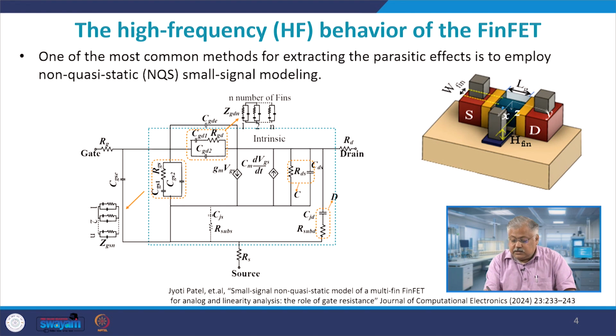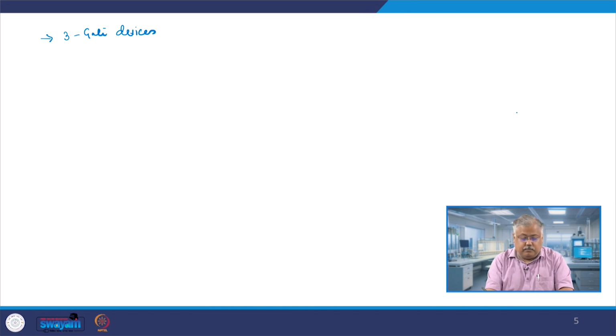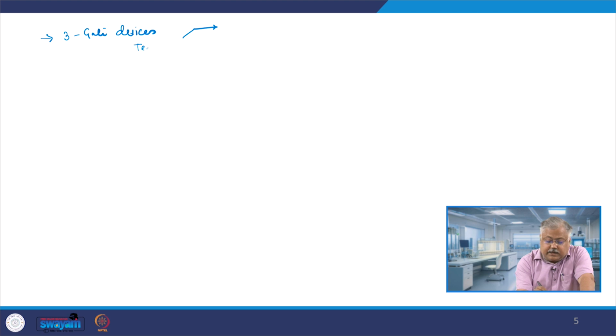So if you make this top gate oxide layer very thick, the gate loses control over the top gate, and a tri-gate converts to a double gate device. Where do we use this high frequency test cases? What are the test cases here? The test cases are basically 5G transceivers where we use it, right.